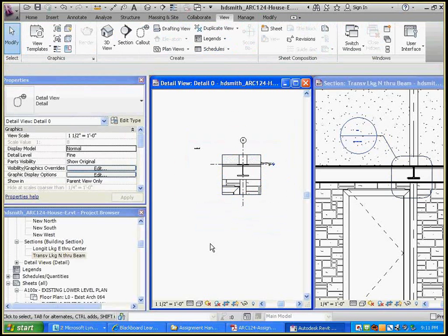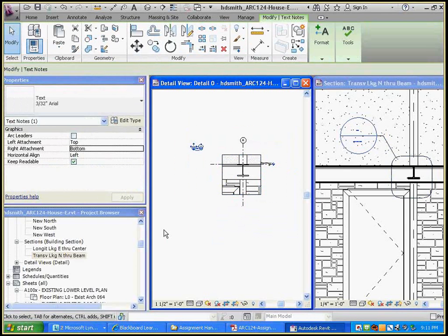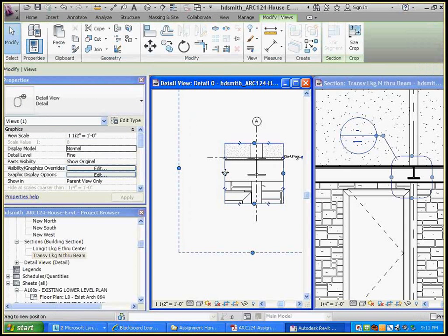The idea is that you can put details on a sheet, and then when you're working in the detail, you won't get your text to where it's going to start spilling over on top of another drawing on the same sheet. But it's easier to go ahead and work in the sheet, in my opinion, and we'll see that in assignment J. So anyway, I want to make that view so that I'm not looking deep enough to see what's beyond. I only want to see the column, but not the door and the stone wall beyond.